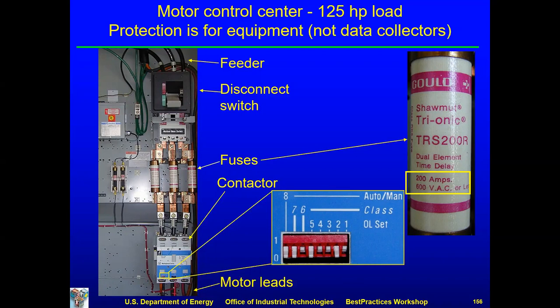One reason is they run smoother because you've got those 3 phases. If you put it all in 1 phase, you've got basically 60 cycles like this. But when they space that out in time, you've got 1 phase here, 1 phase there, I guess they're 120 degrees apart.